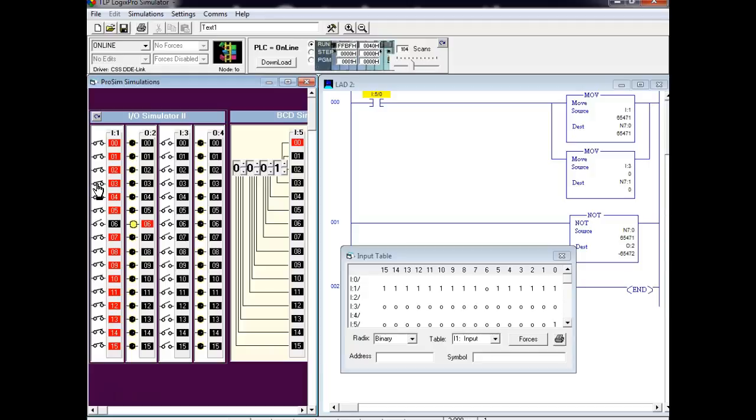We went ahead and put those two moves, so when we start dealing with our logic, I have two operands that I'm bringing in to AND together or OR together, right? When we do a NOT, how many operands are we dealing with? One. Okay. So I'm getting my operand from which input? Input 1. N7:0, which is coming from input 1. Right. Okay, you understand? Input 3 is not being used. Well, it is, it's just that we're not using it later on.